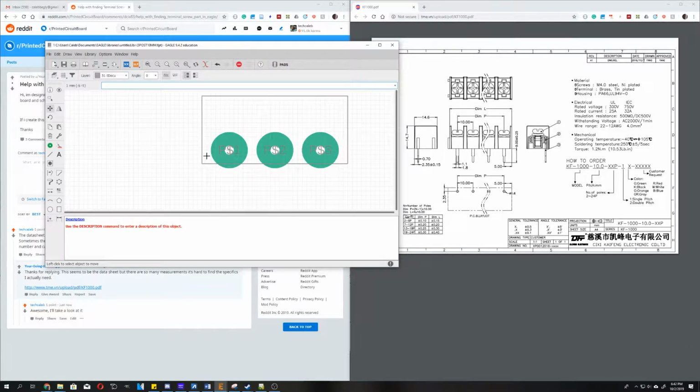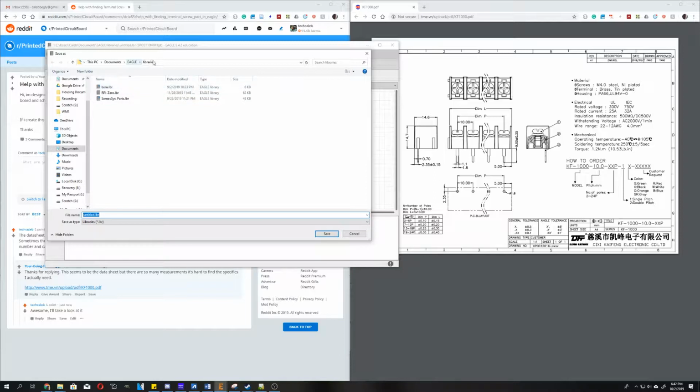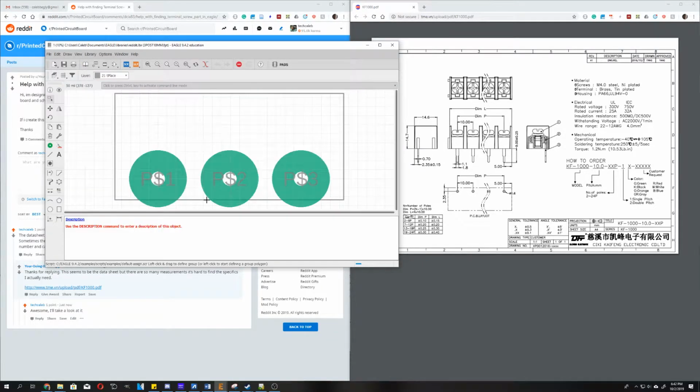And this line just shows where you don't want to put any components because the connector would end up on top of that. So now we'll save that. Maybe let's add a few more things. Okay, but first, so Documents Eagle Libraries is the default in new versions of Eagle. Let's call it that for now. I don't have a library picked out for that. You can always go back in the footprint and edit here.